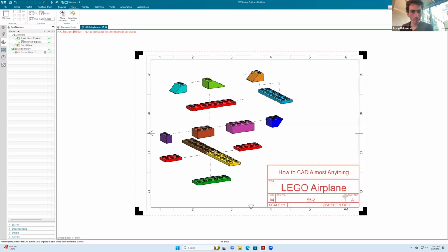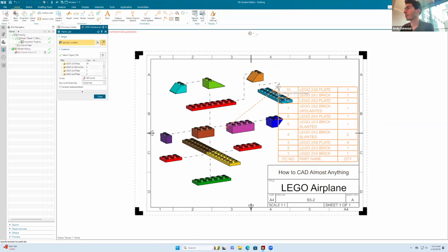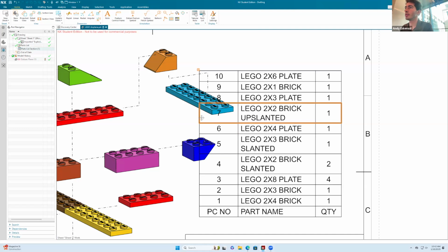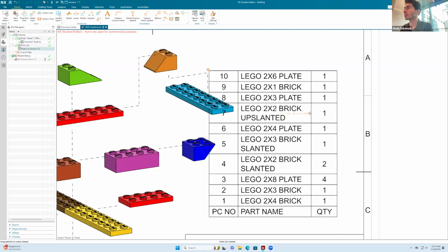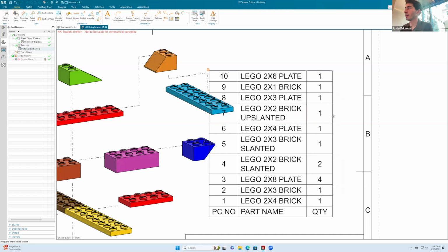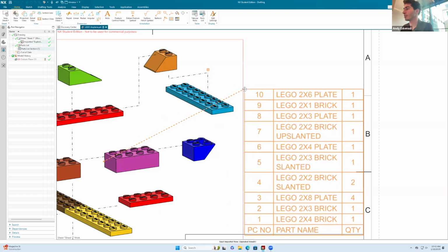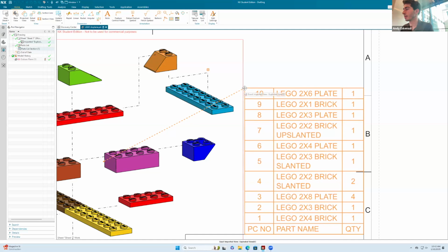Fortunately, it did save in here what we had before, but now we're going to drafting. Oh, there we go. So parts list. I'm gonna bring this bad boy over here, and I'll just edit the size of our table. That way it's as thin as possible, and ideally this should nicely fit right there.